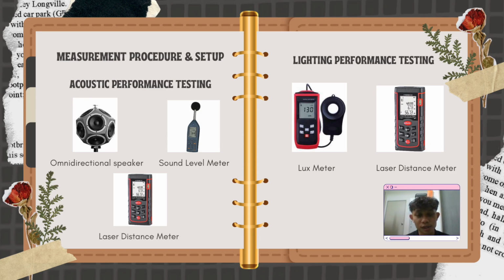So the steps for sound measurement: firstly, we need to empty the hall, so we made sure the room was empty and quiet. Next, we measure the room. We measure the hall's length, width, and height. Next, we make a grid. We mark 24 spots on the floor evenly.